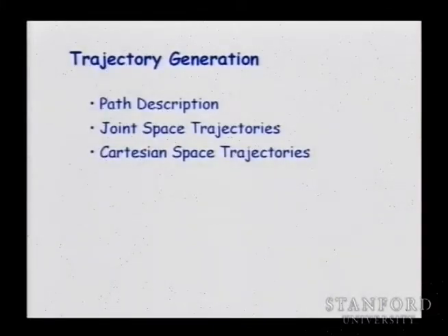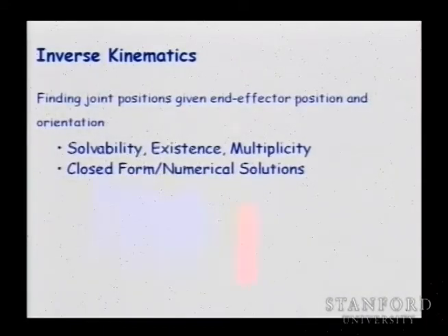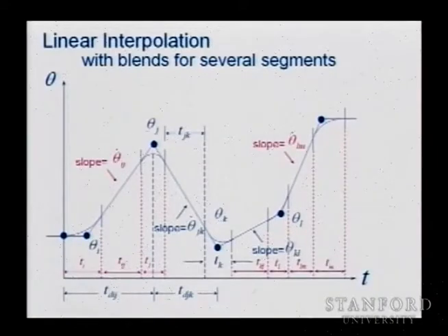And then using those solutions, we can then do this interpolation between where the robot is at a given point and then how to move the robot to the final configuration through trajectories that are smooth both in velocity and acceleration and other constraints that we might impose through the generation of trajectories both in joint space and in Cartesian space. So, I'm going backward now. These will result in those smooth trajectories that could have via points, that could impose upper bounds on the velocities or the accelerations, and resolving all of these by finding this interpolation between the different points.